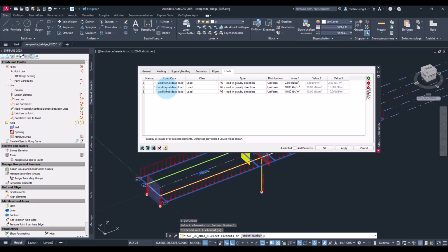So I will add two loads. The first one for the load case 81 extension, and then one for 82 contraction. These are temperature loads, and basically a temperature difference extending in local X and Y direction.